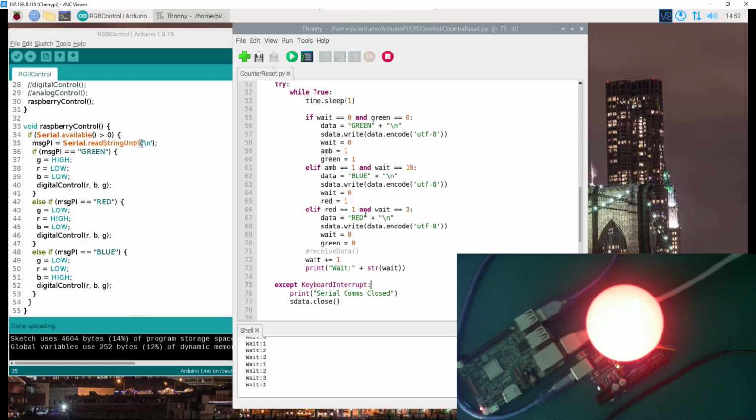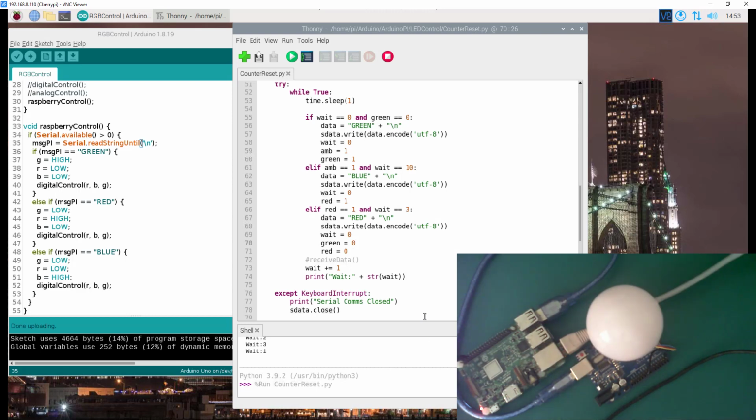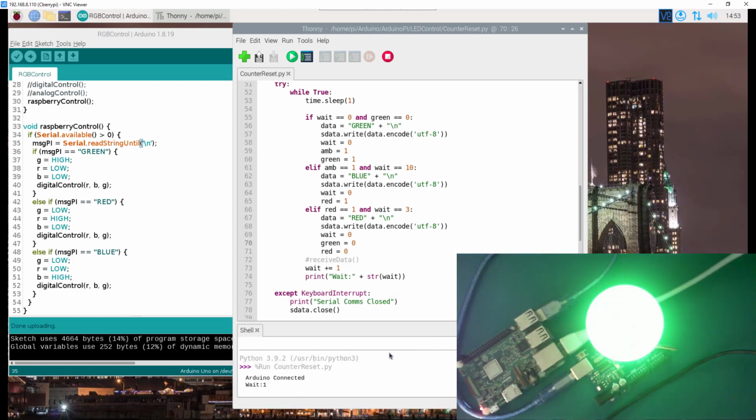How do we get out of the red signal here? Because this, okay, this is executed when red is equal to 1. So we basically need to put red to be equal to 0. Okay, so when we put red equal to 0, then we will not execute it again. The only time we're going to get red to be equal to 1 is when we execute amber, okay, or the blue. That's when after that we're going to get red equal to 1 again, and then we'll execute the red. So let's give this a try and see whether we have indeed resolved our problem.